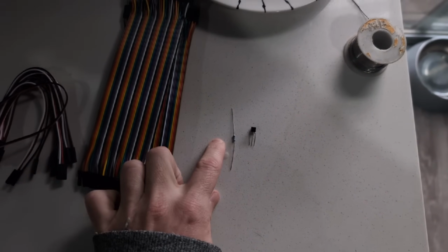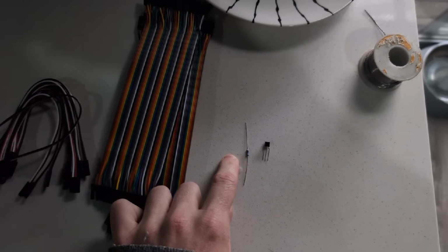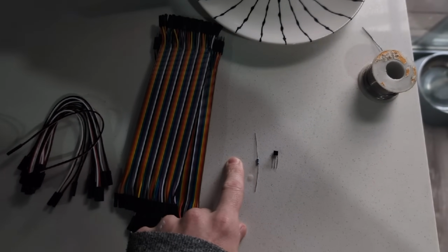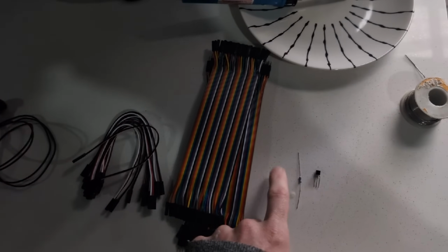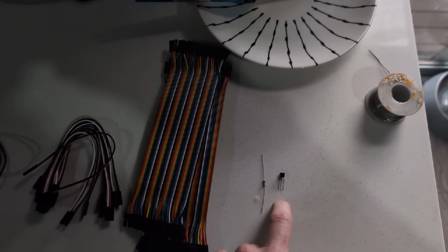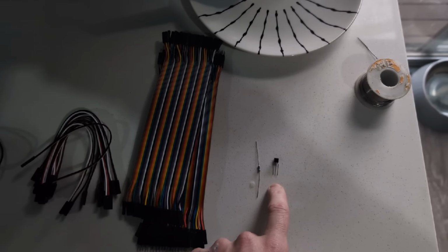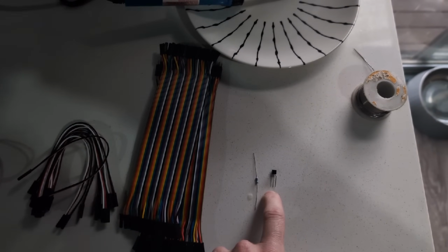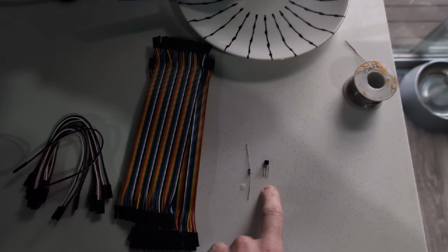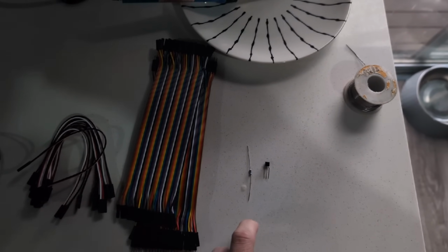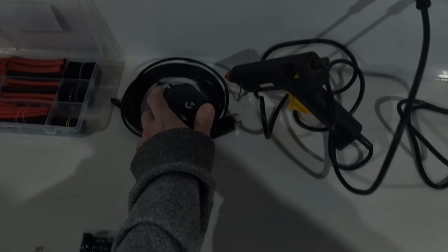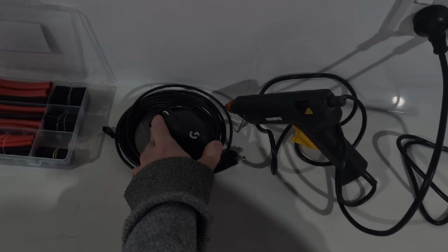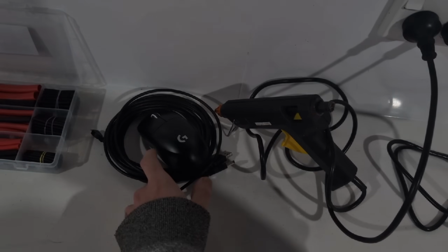The 220 ohm resistor for the mouse switch, because the mouse switch is, I believe, 3.3 volt, not 5. And then a transistor for switching the mouse switch to toggle on and off from memory. So you don't have to sit there manually clicking the mouse to do each test. I do have a config where you can, but that's just annoying that way.